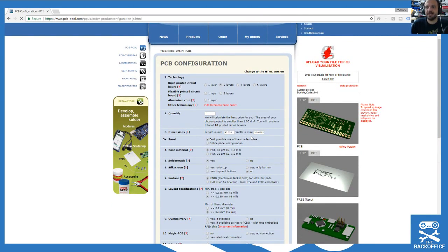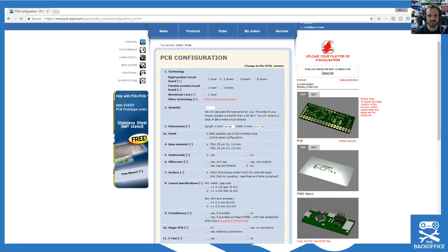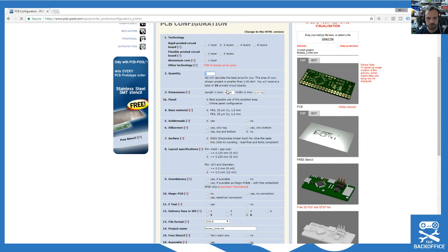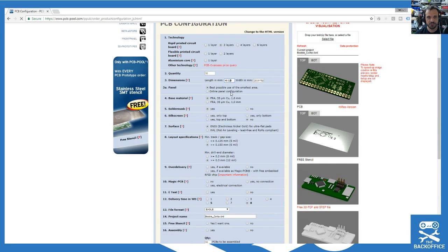So yeah, Ash is saying there, on these things you used to have to upload your Gerber files and stuff, and then they'd go through and say there's a problem and there's a massive cycle time. Because now you can just send them your Eagle file, it just processes everything, so it works out all the lengths and widths, so you don't even have to do the pricing yourself. So it knows it's 2 layers. Should we put it on a flexi? No. So yeah, I'm going to have the 10. I'm going to put 10 in. Let's see.